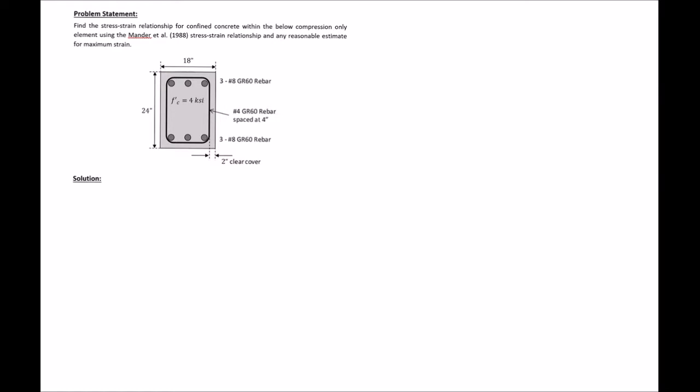In this example problem, we're going to find the stress-strain relationship for confined concrete for the given section. We're going to look at our compression only, and we'll use the Mander et al. 1988 stress-strain relationship to make a reasonable estimate.